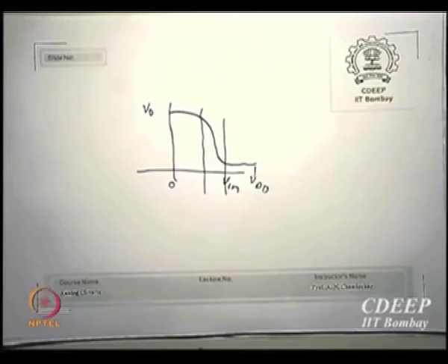Few millivolts. Do you get the point? Because during this few millivolts only V0, Vin has relatively linearity, nowhere else. Okay. So what does that mean? The input signal in analog has to be small signal because otherwise it will not remain in linear zones.